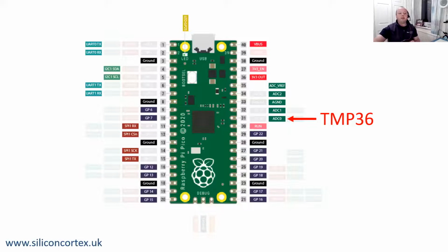But of course, if you go and buy other sensors, it's still every man for himself, like with the Arduinos. So don't expect to be able to go and buy a temperature sensor or an environmental sensor and a display and think they're going to be able to work together. I guarantee you will find a pin conflict. So the proposal here actually gets around any pin conflict problem and still gives you full control of any peripherals you want to nail onto it.